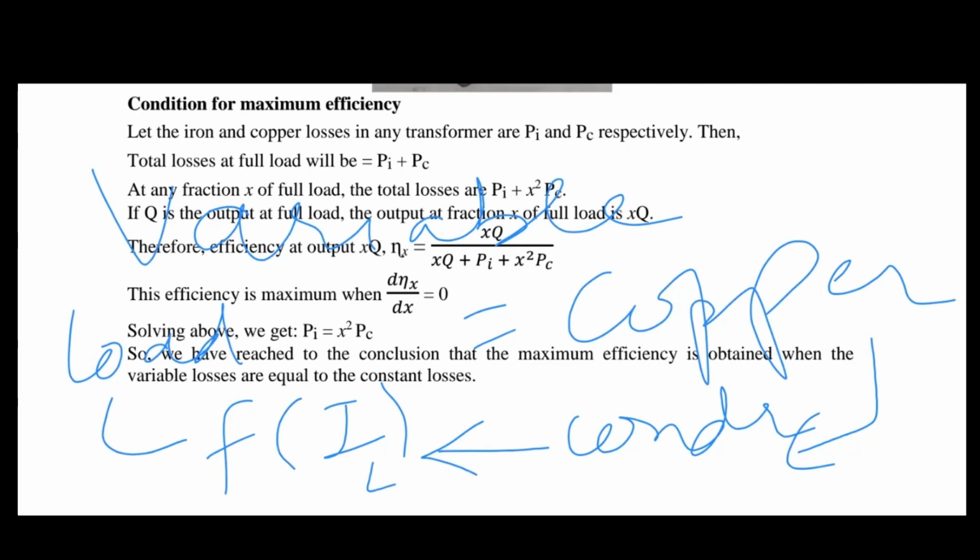Whenever you use electricity, the current is consumed, that load current is drawn from the distribution transformer, and that is drawn through the conductor, and conductors are made of copper. So these are copper losses. And why are they called variable losses? Because our current or the load requirement changes every second.